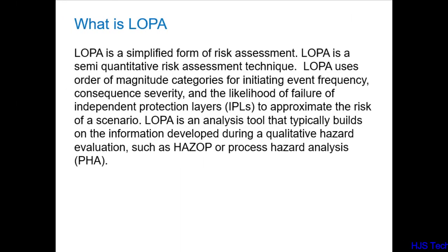Layers of Protection Analysis (LOPA) is a simplified form of risk assessment, and a powerful analytical tool for assessing the adequacy of layers of protection used to mitigate process risk. LOPA is a semi-quantitative risk assessment technique. LOPA uses order of magnitude categories for initiating event frequency, consequence severity, and the likelihood of failure of independent protection layers (IPLs) to approximate the risk of a scenario.